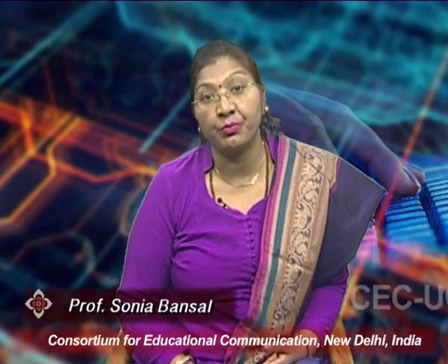In the previous lecture we discussed the conductive ink. Now we discuss the semiconductor ink, which is also the core component of printed electronic devices and largely determines the performance of the final devices. We choose the semiconductor ink on the basis of its performance, and we divide this ink into two categories: organic and inorganic semiconductor ink, which will be used for the next generation two-dimensional material ink.